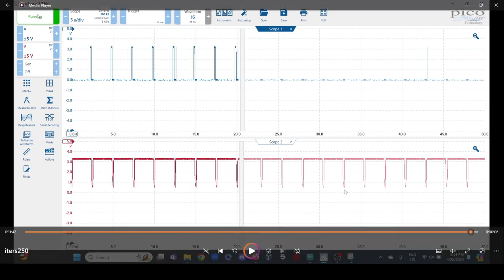So with this, I conclude this video by concluding that we have used intermittent computation to store the intermediate state of our cryptographic algorithm iteration number in the non-volatile external flash memory, which is connected to the Adafruit Metro M0 Express board, and we retrieve the intermediate state from the non-volatile flash memory every time the power comes up, and that's how we progress towards the execution of all the number of cycles.